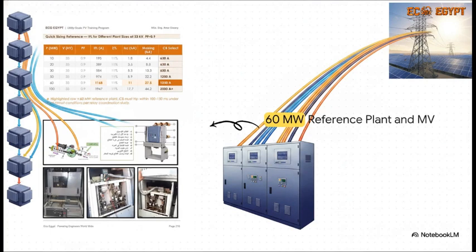And this brilliantly illustrates the sheer physical scale we're dealing with. To manage the power from all those inverters, this 60-megawatt plant needs 6 separate transformer stations, each rated at 9 MVA. From there, it all feeds into a heavy-duty medium-voltage switchgear featuring 12 individual cubicles. That switchgear collects all this generated power and safely exports it right to the grid.